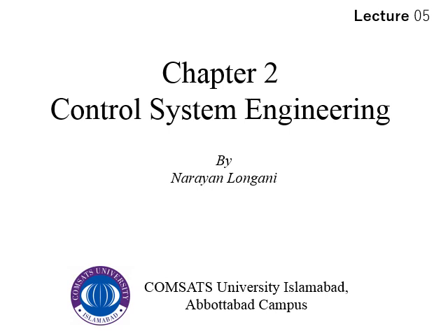In the last class, we studied about operational amplifier and how to find transfer function for two basic configurations of op-amps. The first one was inverting op-amps and the second one was non-inverting op-amps. In case of inverting op-amps, as the name implies, output of the system was out of phase with respect to input, whereas in the case of non-inverting operational amplifiers, output of the system was in phase with respect to input.